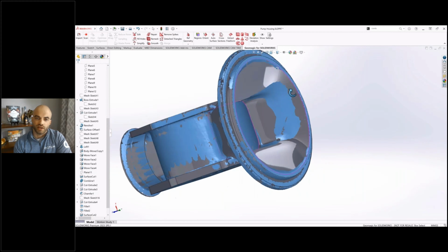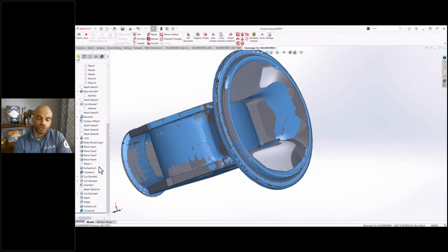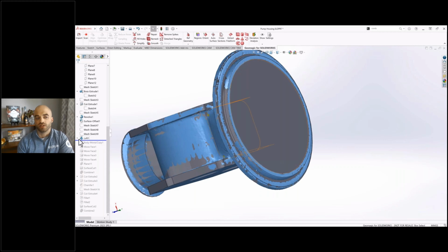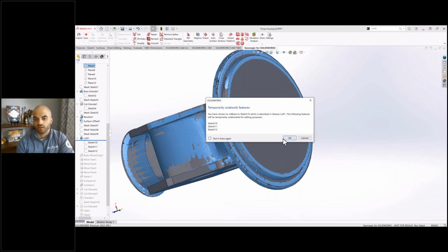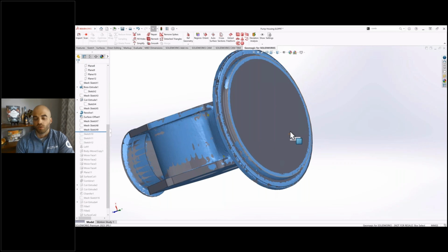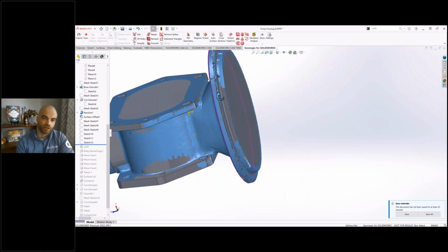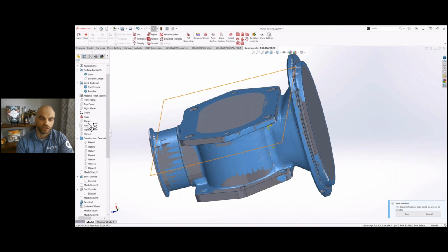Now for this inside surface, generally with a loft, like I said, I'm placing cross sections at areas of changing curvature. And usually that's good enough to get what you need. But obviously here we missed some behavior in the middle there. We could do another guide curve, or we could do another cross section. I chose to do another cross section.